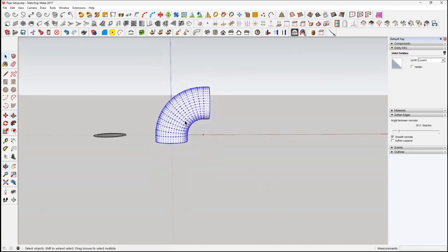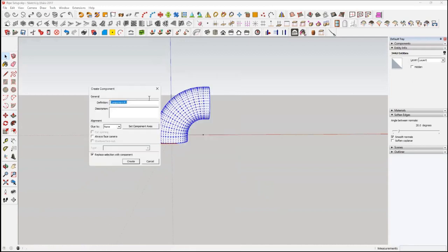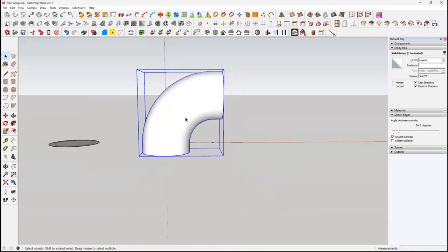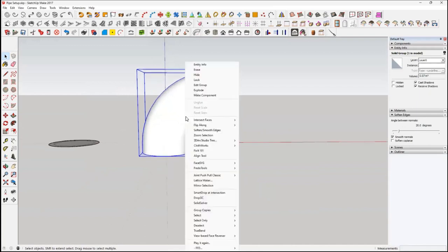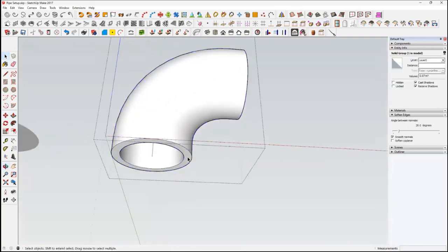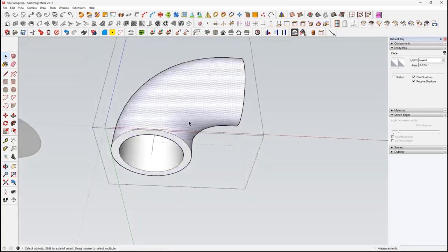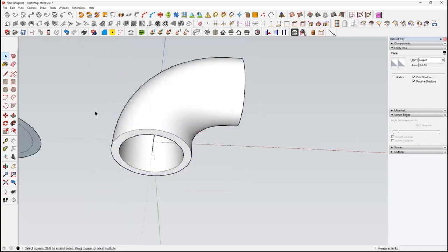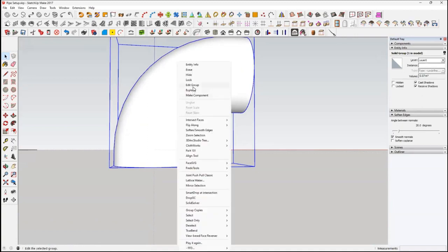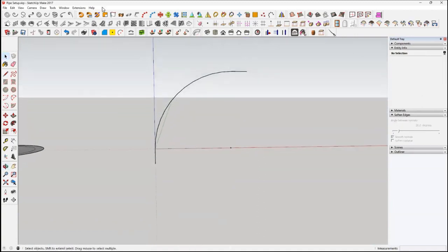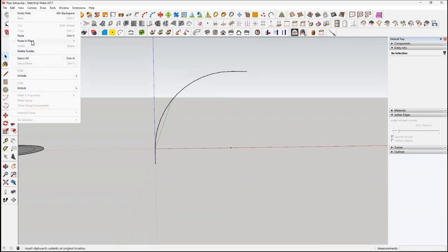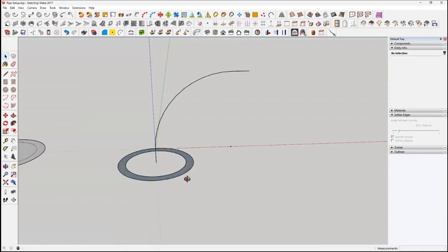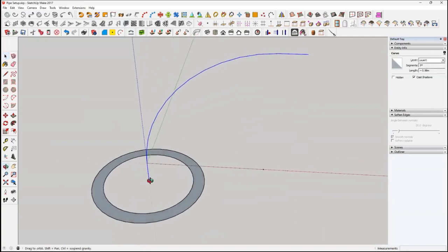So we'll triple click this object, right click, make a group. And then we'll right click. Actually, what we'll do is, see this ring at the bottom, we'll double click the group to open it, click on the ring, and we copy it. Then we'll click on this object, right click, and we'll hide it. And then we'll do an edit, paste in place. So we know that's the diameter of the post. Now, we don't want this one, but we can still use it because it's bang in the center.